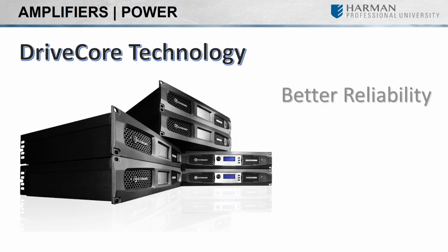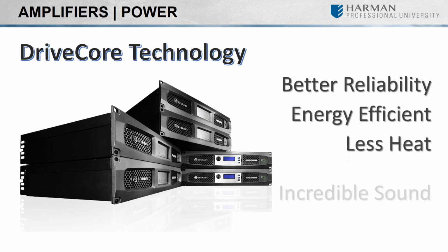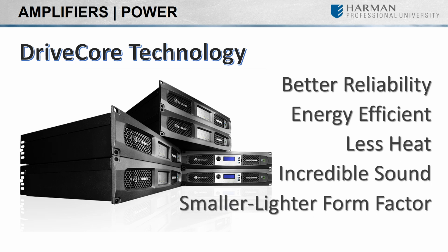Crown's focus is on the latter of the two power supply technologies, and many of their amplifiers today offer what is called DriveCore technology. Building on the Class I technology, DriveCore's front-end drive circuits leverage the inherent efficiency of Class D output stages while also maintaining superb sonic characteristics. The end result is an ultra-efficient, one-piece audio amplifier circuit that exhibits the exemplary audio quality of a highly evolved Class AB design. This new amplifier technology seamlessly integrates the amplifier drive stage into the power output stage, fusing everything into a chip the size of a dime.